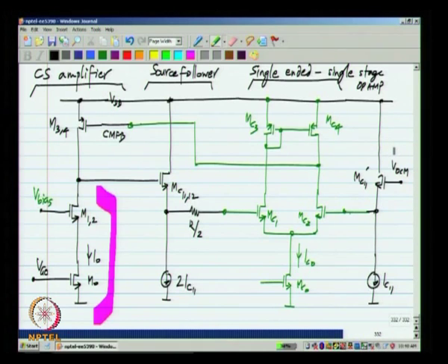So, the part that I have drawn in green plus the transistors M3, 4 will act like a 2 stage op amp, and it happens to have an additional source follower buffer MC11 and 12 in the common mode equivalent circuit. So, whatever we discussed earlier for the stability of the 2 stage op amp will apply here as well.